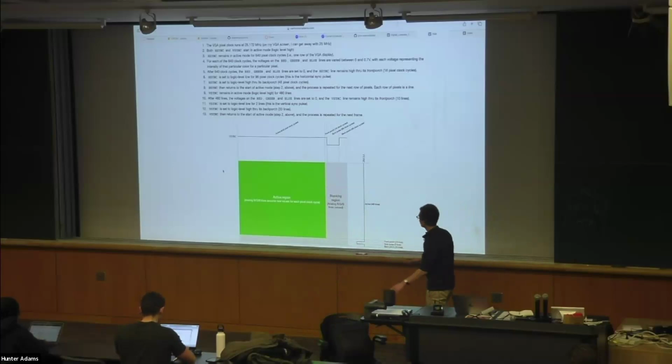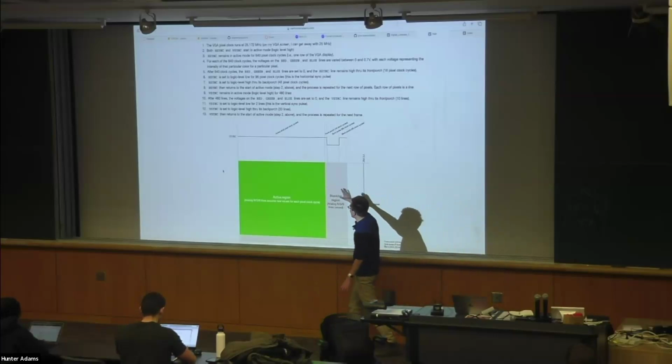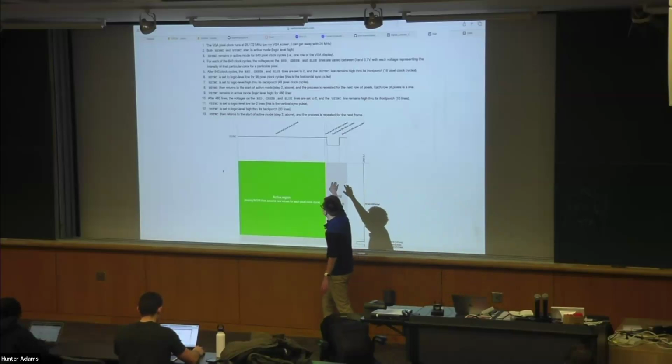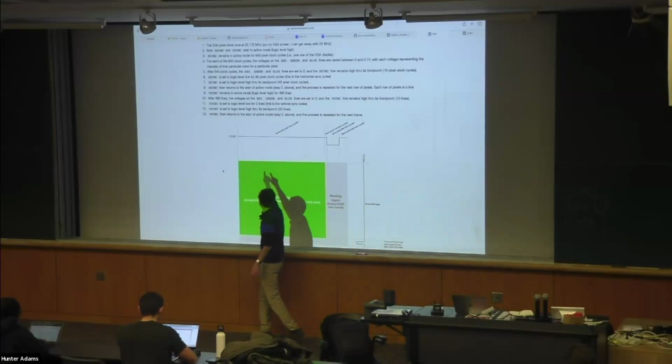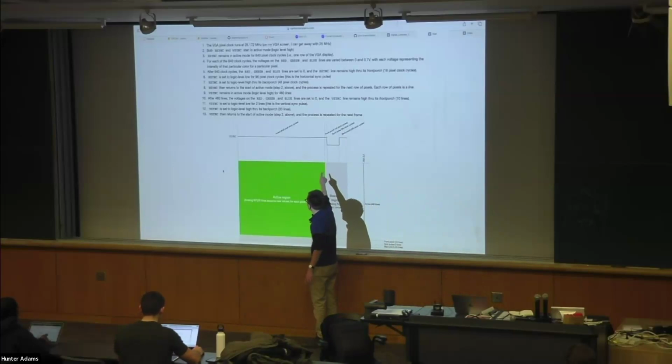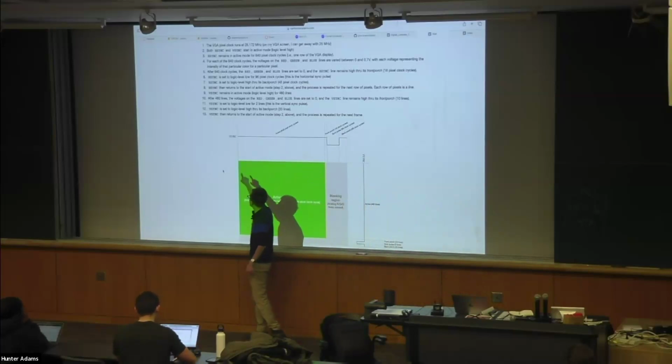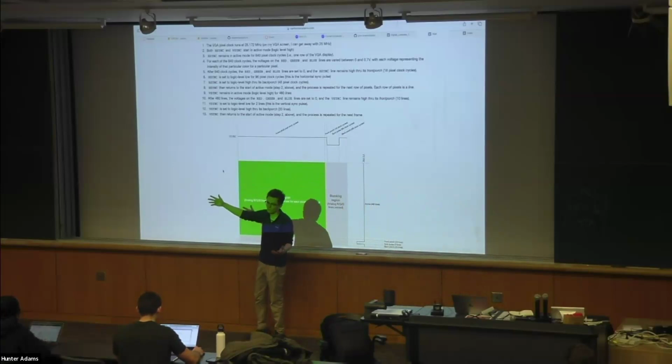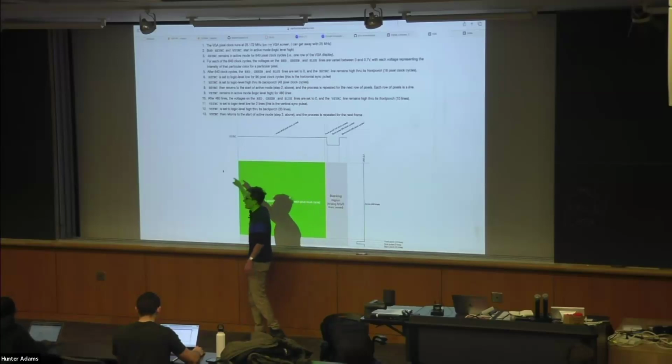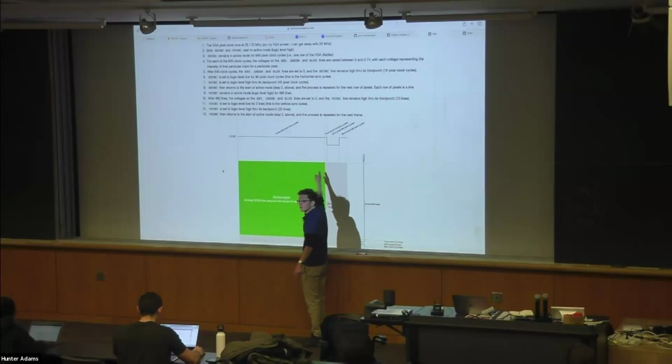Let me remind you how the timing works here. Our H-sync timing line stays high the whole way across a row of the VGA screen, right? So if we want to start writing to the VGA screen, H-sync is high, and then at 25 megahertz, 25.172 megahertz technically, but the RP2040s are driving this at 25 megahertz, we change the voltages on the RGB data lines all the way across the screen 640 times.